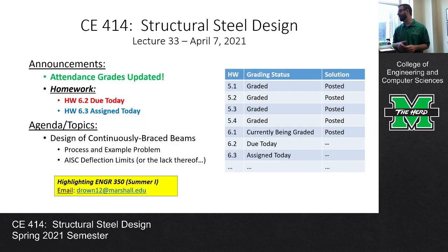To bring in the discussion we were having right before class, we were talking about unit conversions for the beam formulas, the moment, shear, and deflection formulas, particularly the deflection formulas that are in table 3.23, I think it is. You can convert the beam length to inches and not have to use the 1728. That will work only if you also convert any distributed loads to kips per inch.